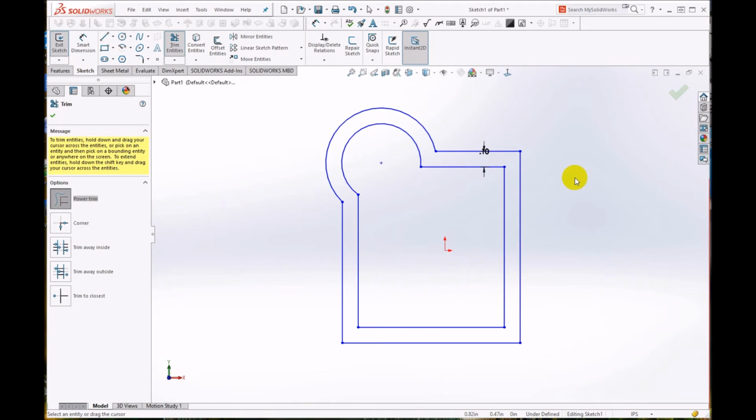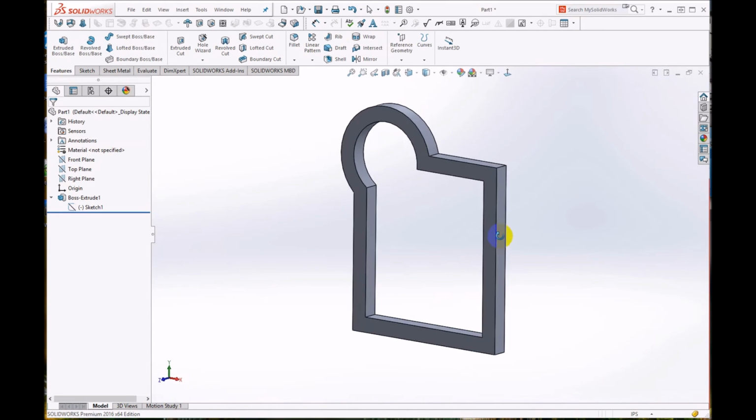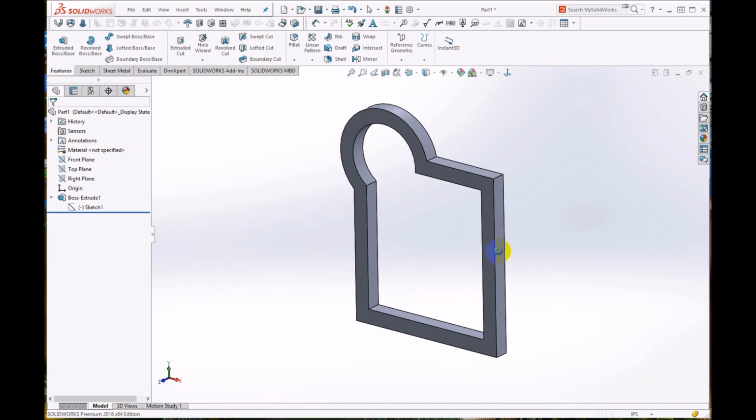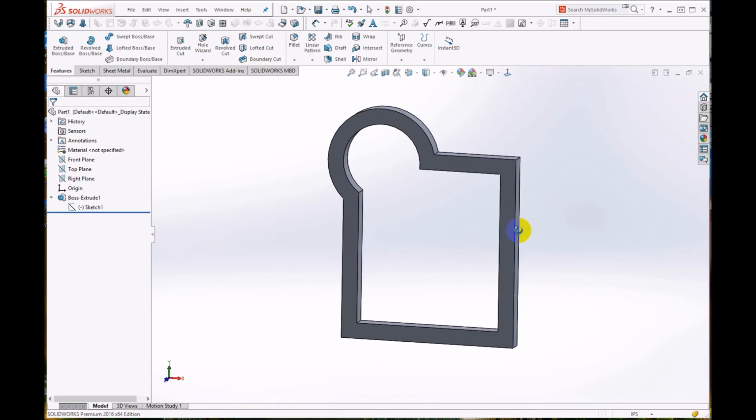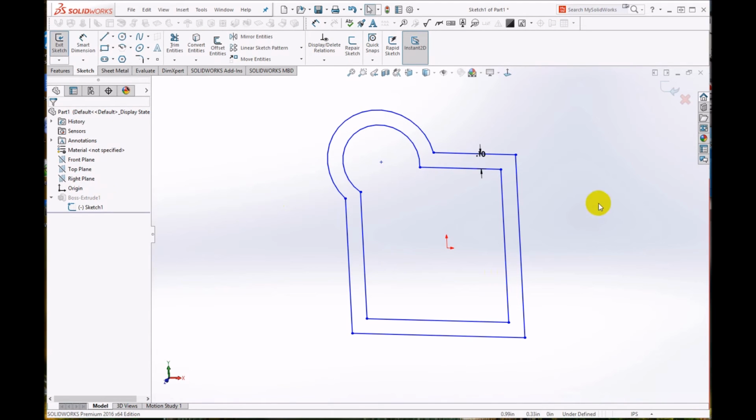And if you were to now finish the trim, finish the sketch, sure enough, it has extruded. It's pretty logical what it does. It is extruded starting from the outside, assuming that the outermost line is the beginning of the part. It extrudes to the next closed shape. And let's go back into the sketch for a minute, and you'll see the outermost shape is this line that goes all the way around. The next innermost closed shape is this thing here. So boy, that's pretty powerful.